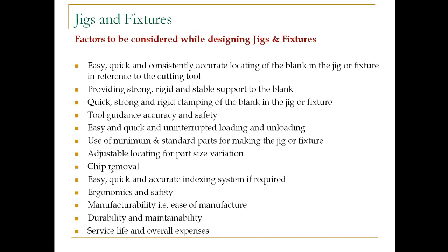The final thing is chip removal. Chip removal should be easy. Suppose you are performing a drilling operation, or an operation on a lathe machine, it should not be that chip removal is difficult or chips are getting blocked in every corner. The chips should be easily removed. Easy, quick and accurate indexing system if required, as we discussed earlier. Ergonomics and safety. Ergonomics means it should be feasible and comfortable for the operator, and obviously safe for the labor.